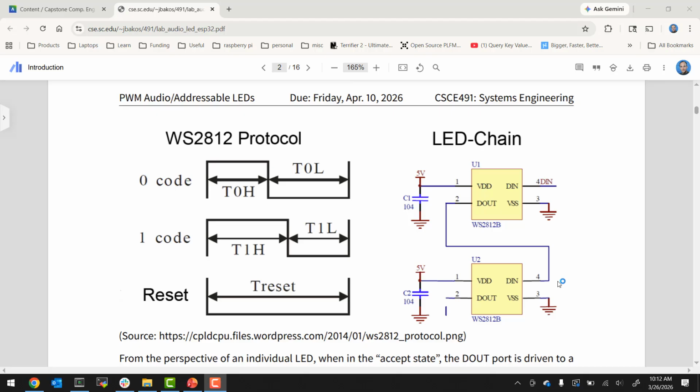And the innovation here is that you have all the LEDs connected on a serial chain, kind of like JTAG or daisy chain SPI, and they're asynchronous. You don't have to worry about sending a clock. And the reason is that each one of the LEDs has its own clock, its own kind of, I don't know, like a wall clock, timekeeping device, like their own crystal.